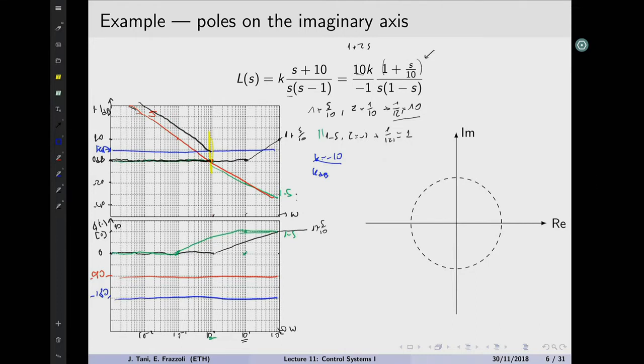So up to here, which is 1 decade, we'll have minus 40 dBs per decade. So this means that roughly we end up here. And then there is this other term that starts contributing positive 20 dBs per decade with the minus 40 of the other side. So it goes down only at minus 20. Oops, this is not correct. It goes down at minus 20 dBs, okay?